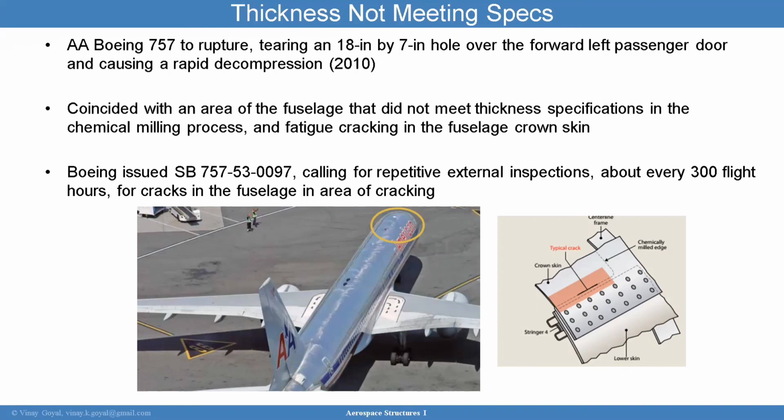The second thing could have been for the person in charge of industrialization to say, well, if the chemical milling process is not adequate, I can damage the dimensional integrity of the part, and that's going to produce this type of failure. Therefore, these are the controls that I need to put in place in my chemical milling process to make sure that I don't degrade the dimensional parameters of the assembly. This is an excellent example, guys, of things that should have been recorded in the FMEA and weren't, or if they were, there were no concise or effective actions that could have prevented this from happening. But good comments and good ideas.